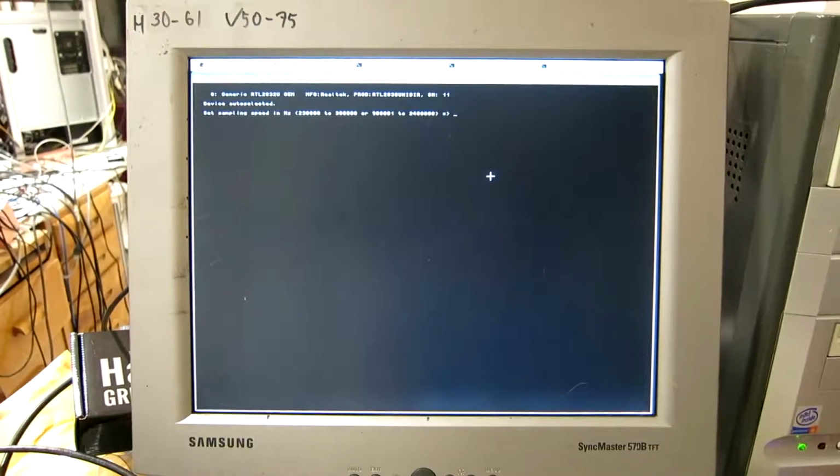Running the dongle at 900 kHz causes a lot of CPU load. It's marginally possible on this computer. I now change to run it on 300 kilohertz, and everything else the same.